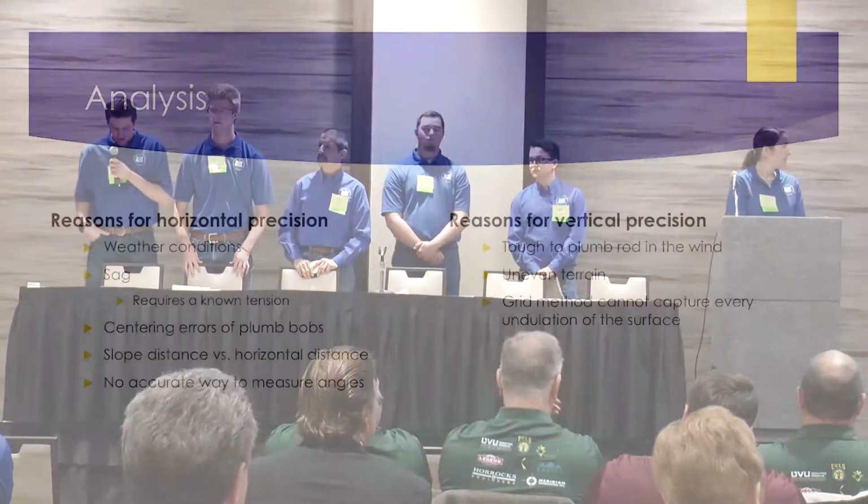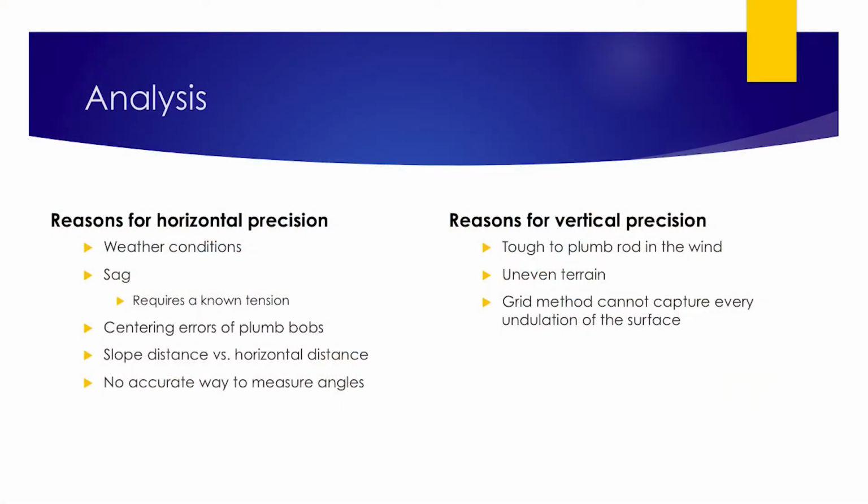Yeah, so some reasons why we got the horizontal precision we did was just because of the weather conditions. You know, all the other teams were out there. Super windy day. It was pretty hard to get that tape straight. Sag, we didn't know how much tension we were pulling, so it was kind of hard to do a sag calculation without knowing the exact tension in which you were pulling. And a slope distance versus our